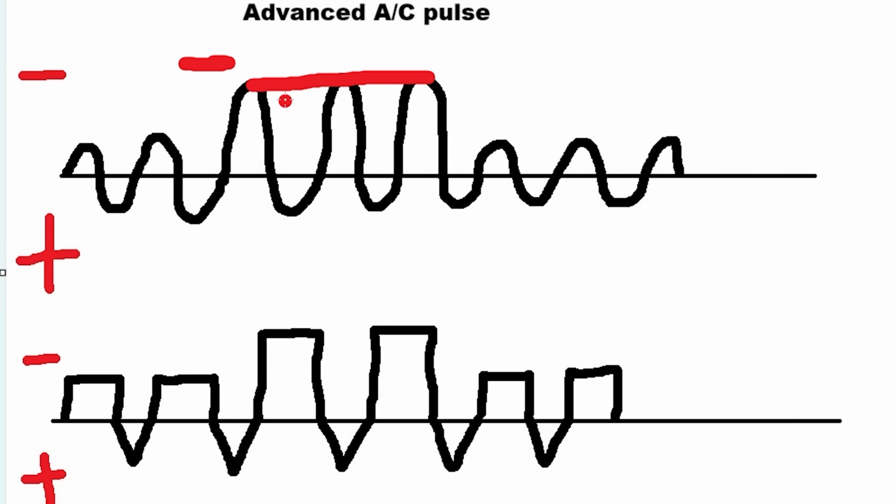Machines that can do that can gain huge penetration on thicker aluminum. You can start seeing 350 amp machine performance when it pulses, for how much penetration you can get. Because again, the whole goal with AC is to get enough cleaning action to clean up that molten pool. But once you have it established, shielded in argon, blasting it, I don't know, once every second and a half with a whole bunch of DC current, like an extended length pulse, can get you a lot more penetration and not really give you a filthy weld pool either.